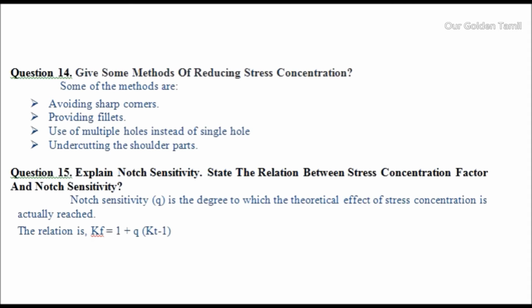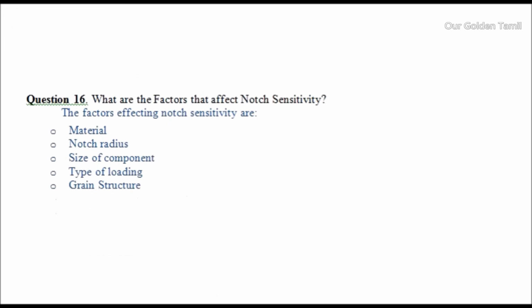Notch sensitivity, q, is the degree to which the theoretical effect of stress concentration is actually reached. The relation is Kf = 1 + q(Kt - 1). Question 16. What are the factors that affect notch sensitivity? The factors affecting notch sensitivity are: material, notch radius, size of component, type of loading,